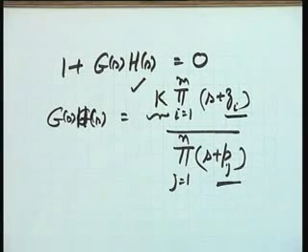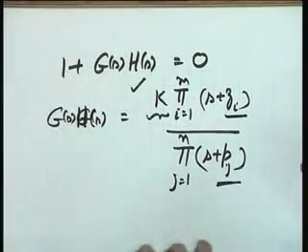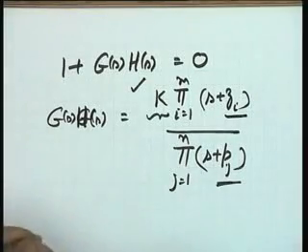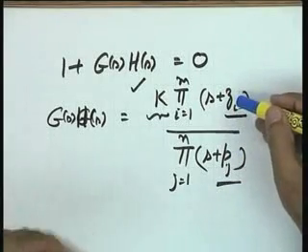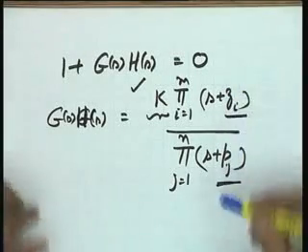Who prevents it? After all, your open loop system can be an unstable system. The purpose of designing the system is to design it to be a stable system. The closed loop poles cannot be in the right half plane, but the open loop pole can be. But in most of the situations we will come across, the poles and zeros of the open loop transfer function will lie in the left half plane.